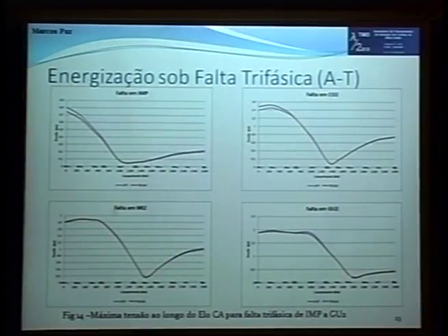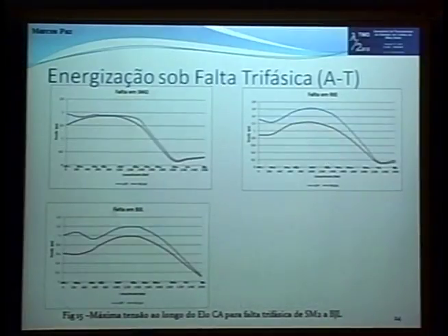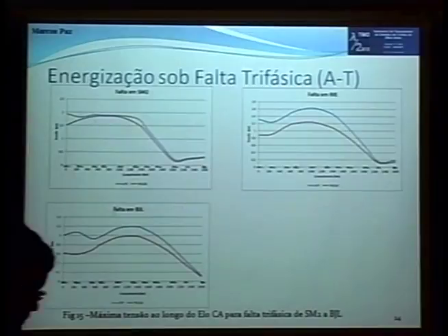So in the following substation in Gurupi, which is about the average point of the most critical region, the overvoltages downstream are going to be limited by the surge arresters working in Imperatriz, Colinas 1 and Miracema 1, and also in Serra da Mesa, up until the fault located in Serra da Mesa, where we have the surge arresters working.